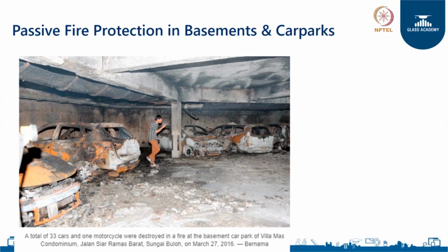So, it is very important to make sure that there is no way that the fire can spread from an area of occupancy into these areas, because these are all narrow shafts that we are talking about, and it is called stack pressure. When there is a pressure difference, fire has a tendency to go into a region of low pressure, and then it just spreads violently into those areas.